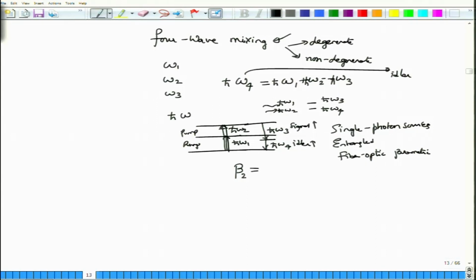If beta 2 is equal to 0, the four-wave mixing efficiency, which is basically the amount of amplified signal power to the pump power that we have totally injected into the fiber, increases. Okay. Whereas when beta 2 is non-zero, that is when there is significant dispersion, this four-wave mixing efficiency will actually reduce. Okay. Now, these equations which I have given are called the energy conservation equations for very obvious reasons.